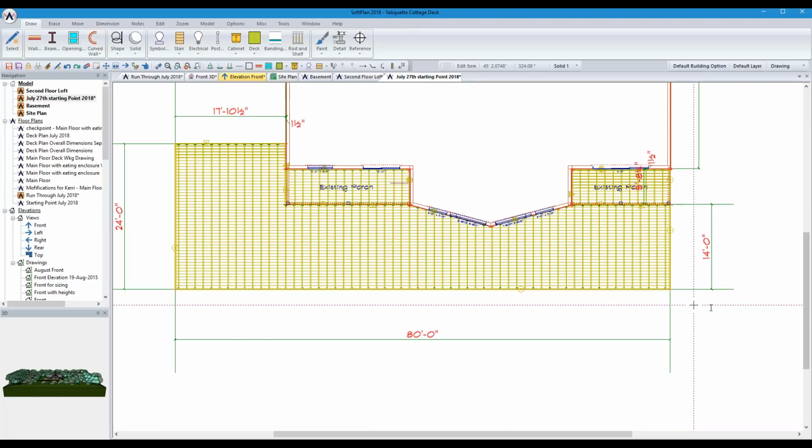Okay, I got a question. Why 9.5-inch joist? That's just the predefined joist depth that we put in. You can set it to what you want. All of our joists are set to 2x10 is drawn at 9.5 inches. That's the way the setup is. If you do put it in at 9.25, it is just a system option that you can change. I assume I'm answering your question, Don.